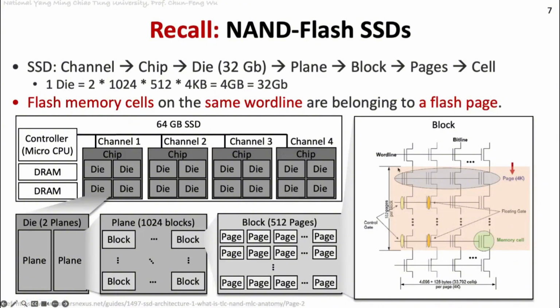So a better way is to make all the blocks, all the cells, be worn out at a very close time. For example, if each cell can only be written like 10 times, then we don't want a few of them to reach 10 times while the rest have only been written 1 or 2 times, right?